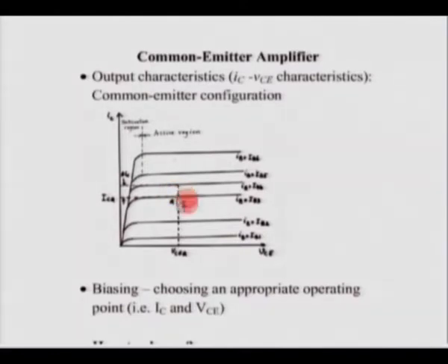Corresponding to that, the collector voltage would change, and later we will see that we would have a collector resistance RC. We need to choose this resistance value at the operating point such that even for the maximum signal swing we are far away from the saturation region and the cutoff region. If not, the output signal will be distorted.